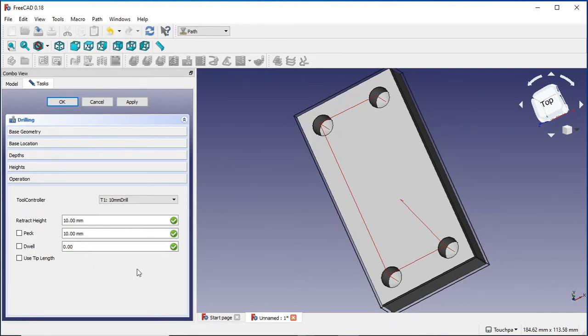The other setting we've got in here is dwell. So dwell is the amount of seconds or milliseconds that we want to stop on our descent into the drilling space. If you think of dwelling as a pause, basically that's what it is, but the tool is still revolving. You would use a dwell if you're drilling a surface that needs to be airtight, like a manifold, or you've placed a small spot drill into the top of the stock, and that drill has to be clean for air to be contained within. As the drill goes in, it will pause, and that will allow the drill to continue a couple of revolutions to clean up that hole, to make it nice and clean without any burrs on there before coming back up.